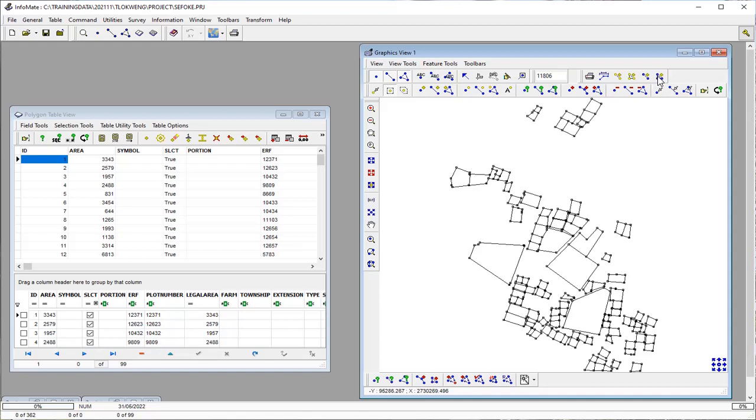We've added an additional two options here. So if you want to just take a selection of your project, for example, I want to take just these points and polygons. I select all the points. I then click this option, which will in turn select all the lines, and this option here, which will select all the polygons. In this particular case, I don't have any lines, but if I had lines, it would select them as well. You can then export that project using File, Save Project As, and that will be the basis of your new project.